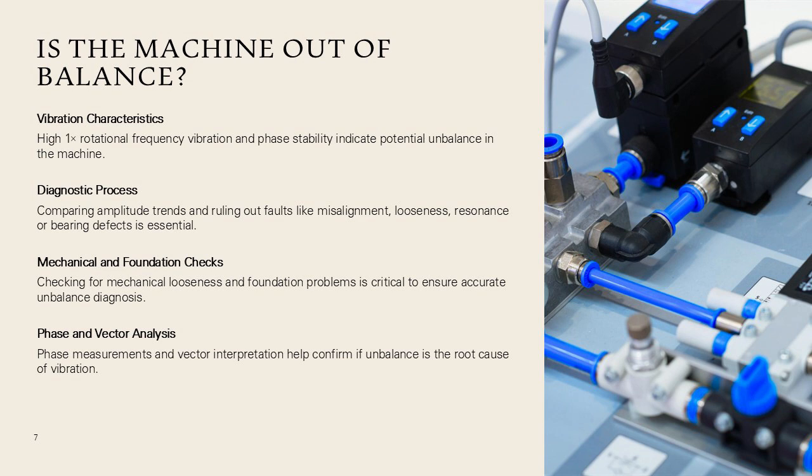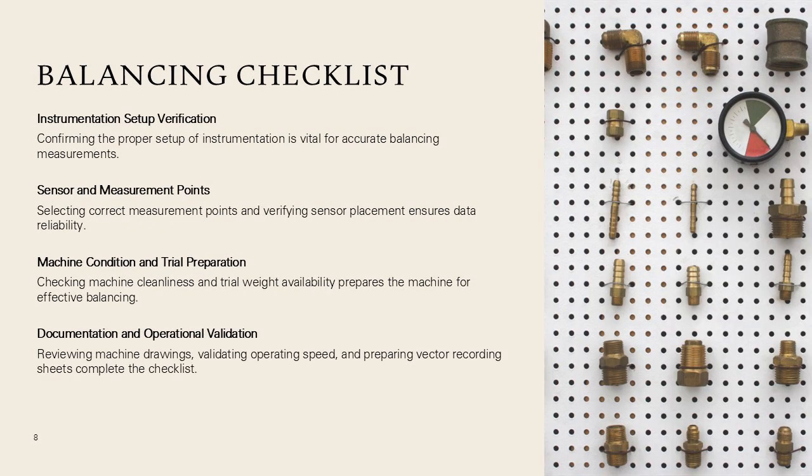It also stresses the importance of checking for mechanical looseness and foundation issues. Phase measurements, vector interpretation, and amplitude behavior with speed changes help establish whether unbalance is truly present. This slide presents a comprehensive balancing checklist.